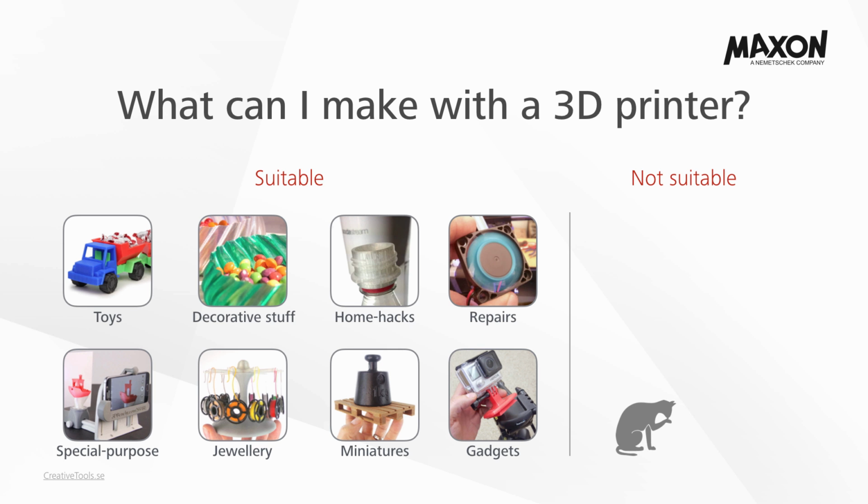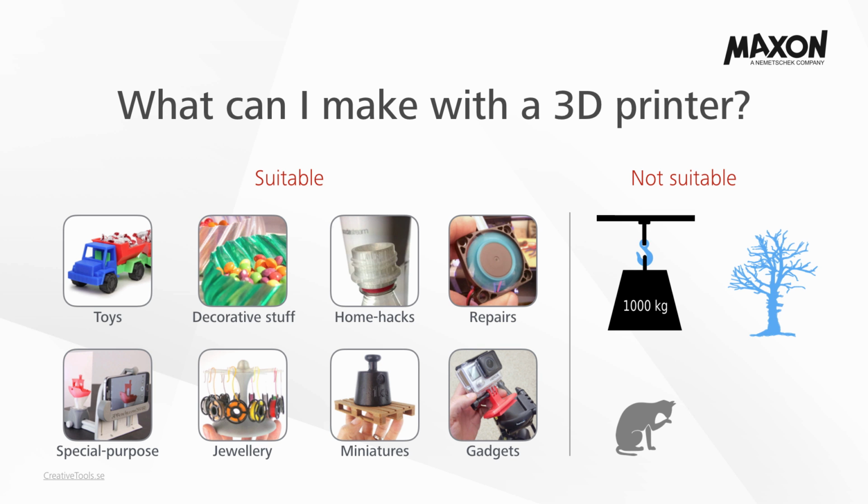There are obviously also situations where a 3D printer is not the best tool. For instance, if you design something that can hurt yourself or someone else if it breaks or fails, you shouldn't use a 3D printer to make that part. Any object with very thin features and very complex shape will be difficult to make. And a big no-no for 3D printing is to make food containers, because you never know how the food will react to the plastic. And generally speaking, sometimes I have to remind myself that 3D printing is just another tool in the shop, and that good old common sense will keep me safe.